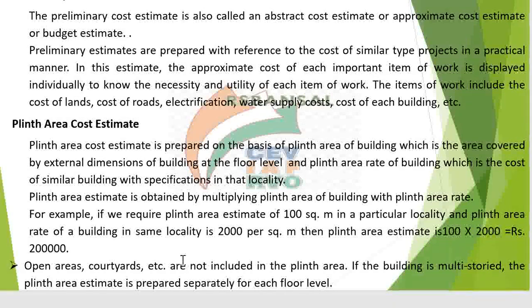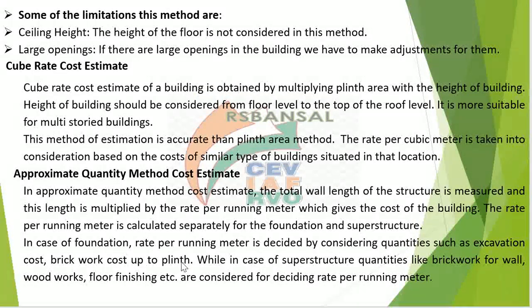Next, some of the limitations of this method. Basically only plinth area, meaning length and width, is taken into consideration. So plinth area rates are mostly based upon a particular height of the building. If the height of the building changes, you cannot use those plinth area rates, because ceiling height is not taken into consideration in this method.